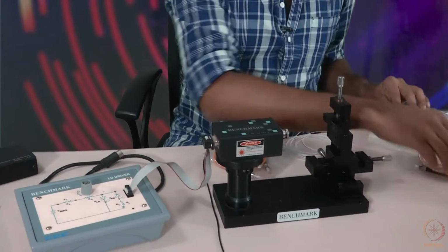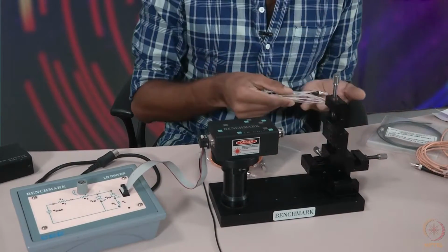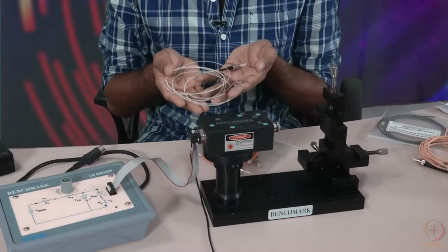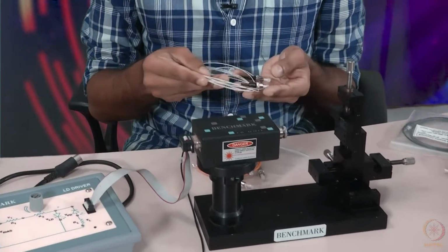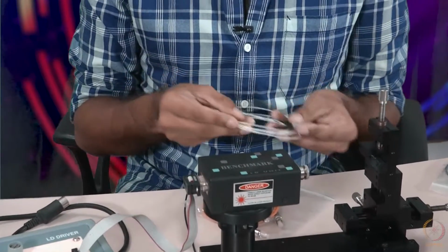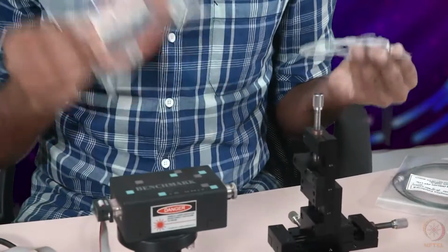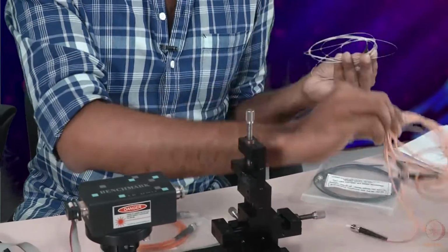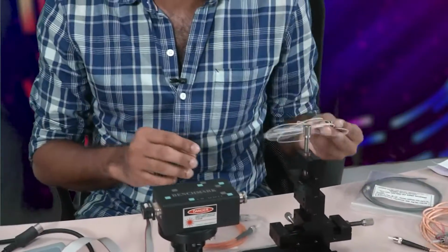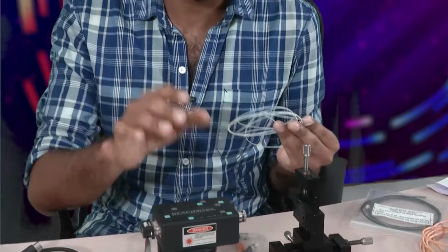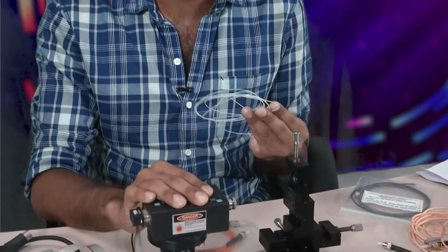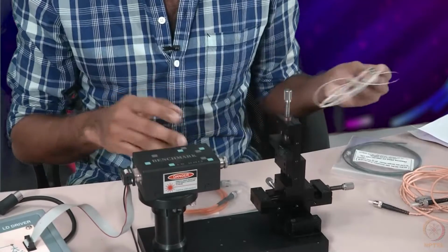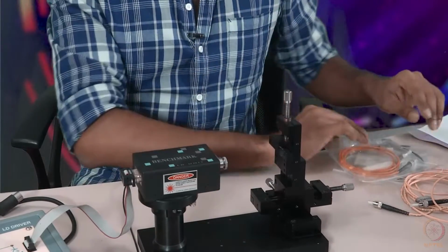Now we see the single mode fiber at 650. This is a single mode fiber 650. This is having a core diameter around 3 micrometer. So you can see the difference, right? This is 60, this is 9 micrometer, and this is just 3 micrometer. At this 3 micrometer, this optical fiber is actually going to be single mode for your 650 nanometer laser. Now that's the fibers that is covered.